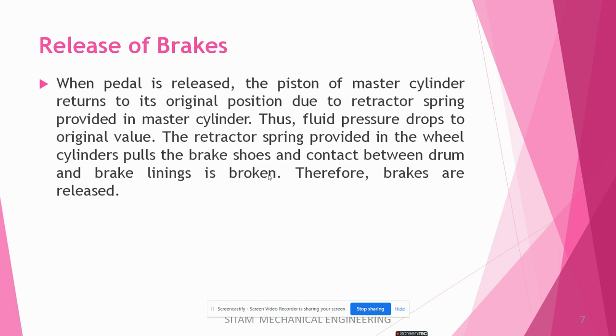Next, releasing of the brakes. What will happen after we release the brakes? When the pedal is released, the piston of the master cylinder returns to its original position due to the return spring provided in the master cylinder. Due to this return spring only, the piston returns to its original position. Thus, the fluid pressure drops to the original value.